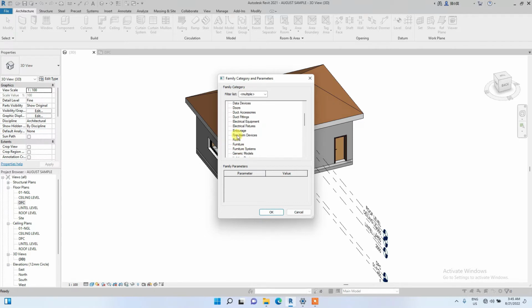But if you click on any of these categories, whether door, floor or ceiling, once you complete the Model In Place, it will have the properties of the item you picked. For example, if I pick walls and create something using Model In Place under wall, it will have the properties of a wall, so you can place doors and windows there. But for this video we'll be using casework to show you the basics.